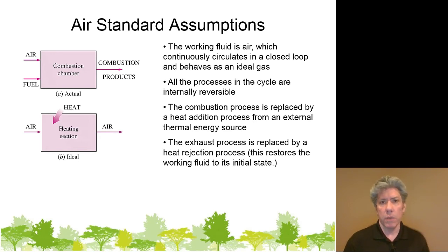And so with reasonable accuracy, you could say that hot nitrogen is what pushes your car down the road, because that's really the purpose of the oxygen and the fuel, at least from the engine's perspective, is to heat up the nitrogen so that the nitrogen will have a lot of thermal energy and can expand doing work pushing the boundary of the piston. So it's not really such a bad assumption to just pretend that the working fluid that's actually pushing the piston down is just air, because that's basically what it is.